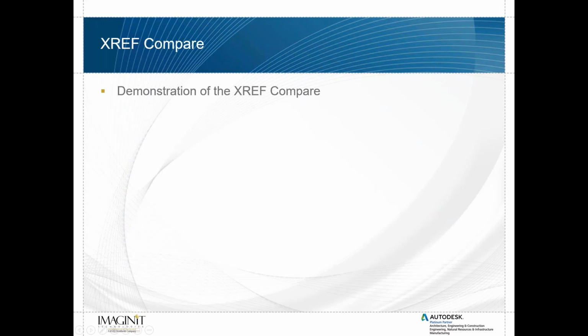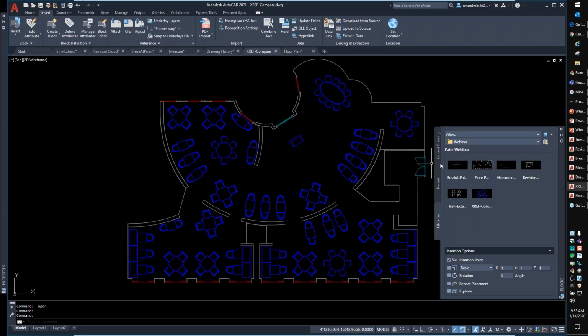Does AutoCAD 2021 fix the wipeout issue? If you're using wipeouts, I would highly recommend you figure out a different method. Wipeouts are horrible. I can explain a lot on why wipeouts are bad things, but that's more of a conversation that I should have with you offline. Usually what I do in those scenarios is I will set a hatch pattern to be color 255, and in my CTB I will set 255 to print at 1% screening. So basically it prints blank, and that's how I fix that problem. Wipeouts are bad.